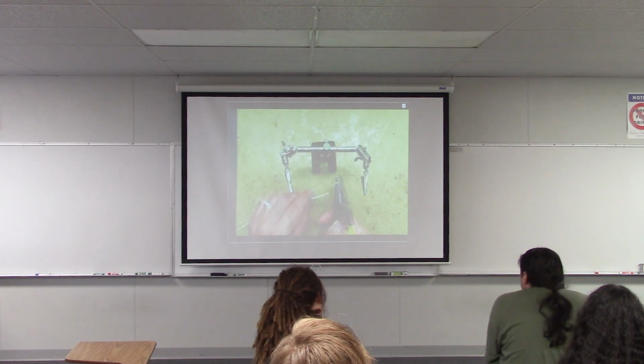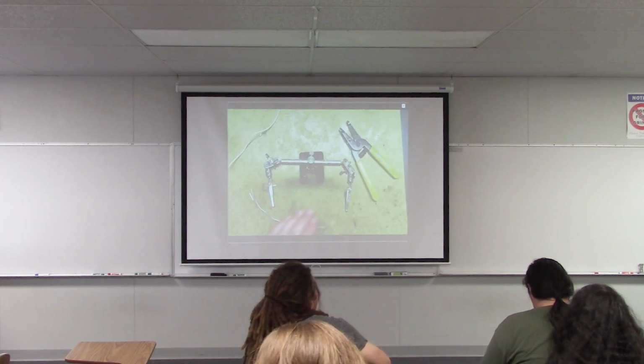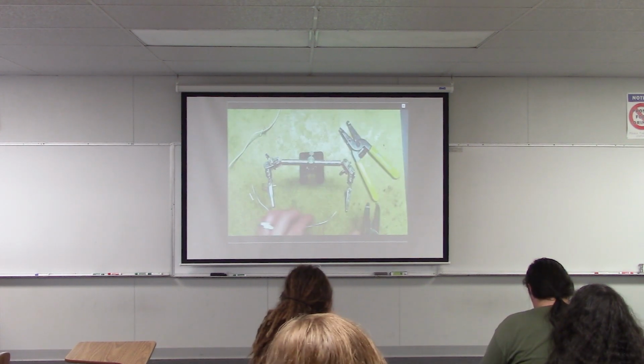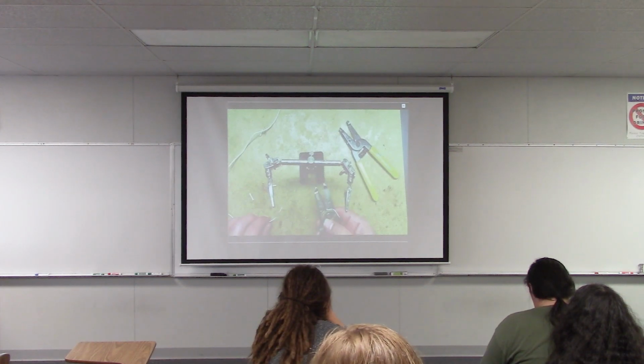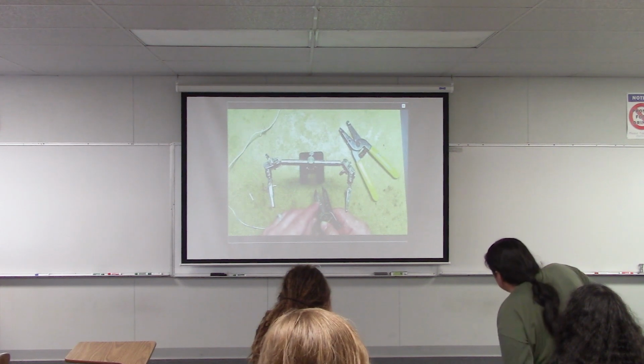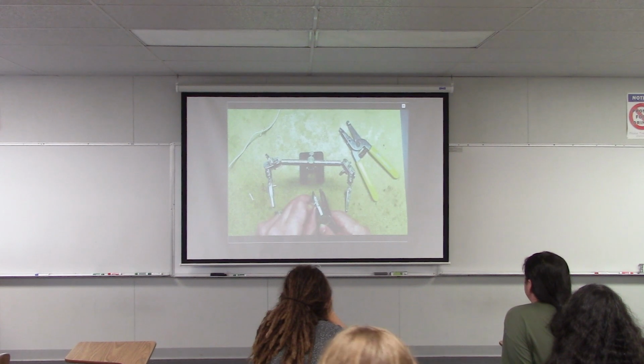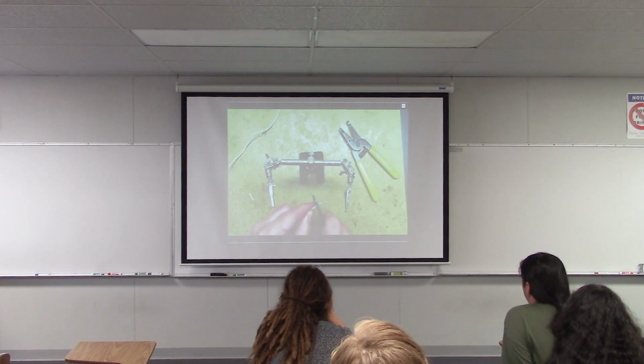What you're going to do is there are different numbers next to these holes that correspond to the size of the holes. So the smaller the number, the bigger the hole is. So this is 22 gauge wire. So what you'll do is you'll find a pair of wire strippers and you'll look for the hole that has a 22 next to it. So on this pair, that hole is right there. So what you'll do is you'll put the wire right in that hole. You'll clamp down on it, and then you should just pull it off, and then it should be stripped.